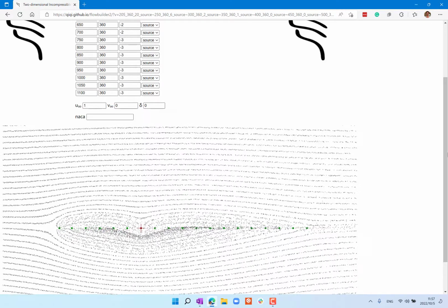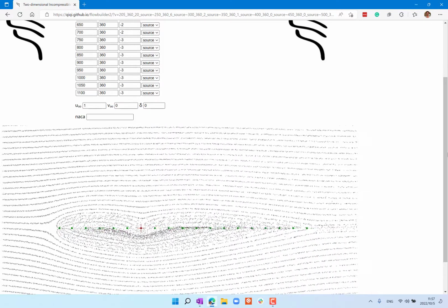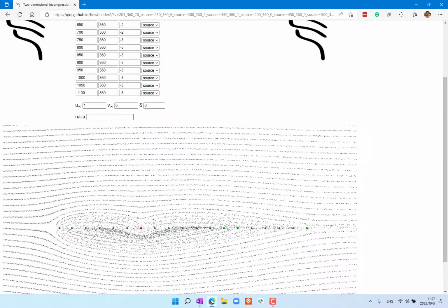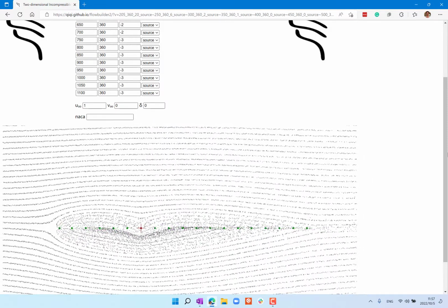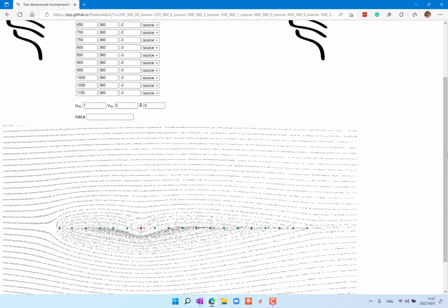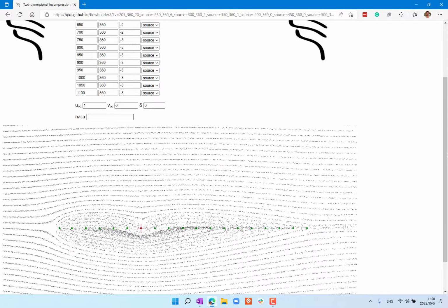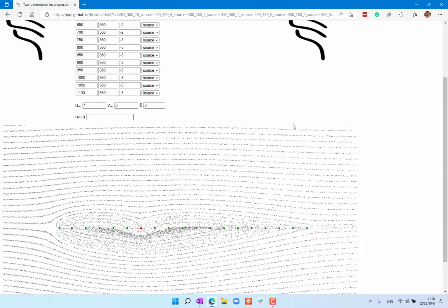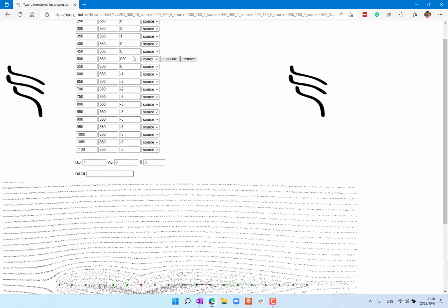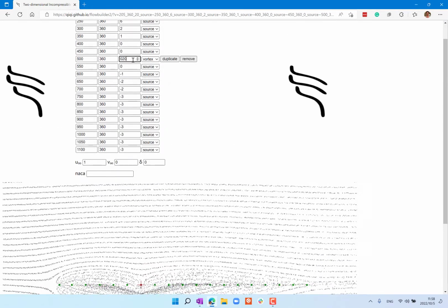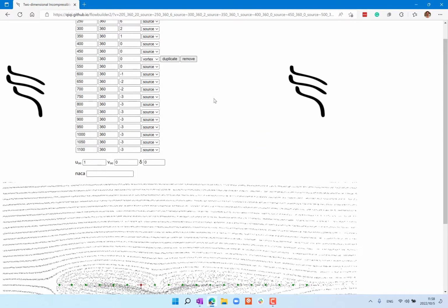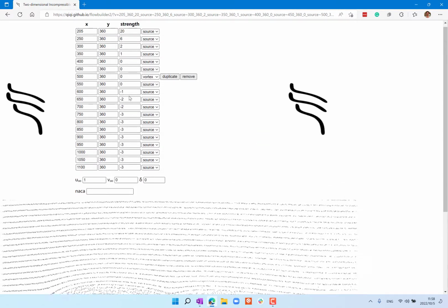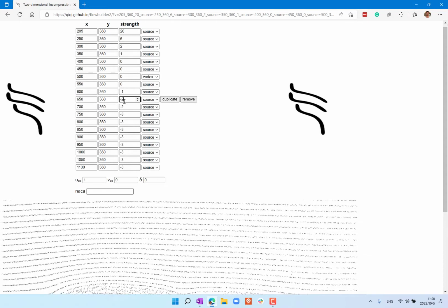Okay. So the connection from the strength of the vortex to what lift you get, what pressure distribution you get, and where that lift is, is pretty obvious, right? So if I want lift centered at the quarter chord, I would basically make that 0. If I want lift centered at the middle of the chord, I would make, is that the middle?